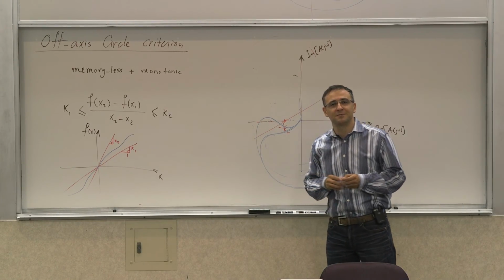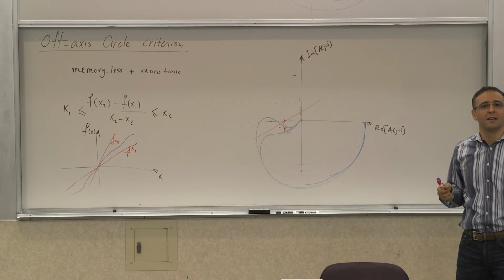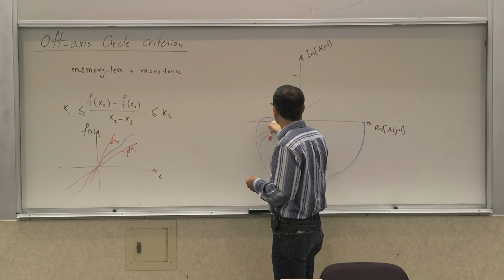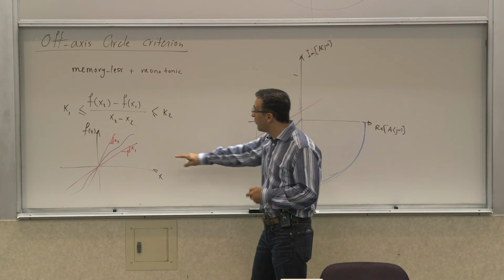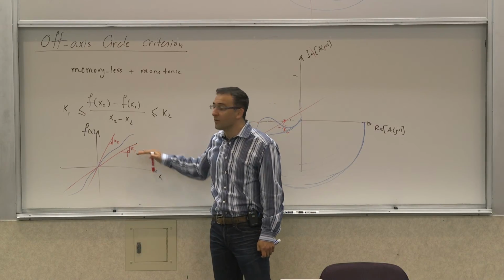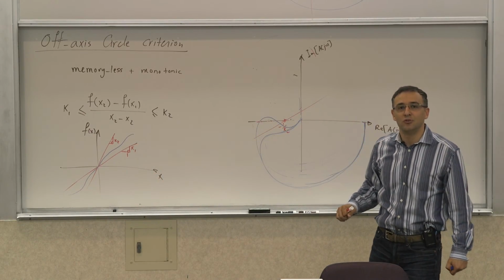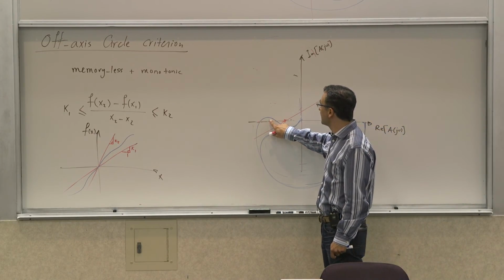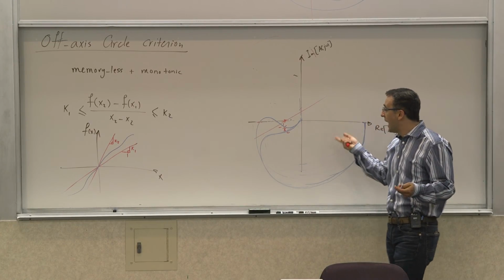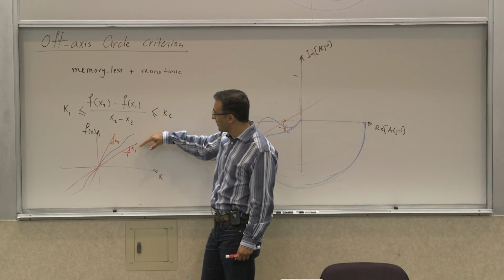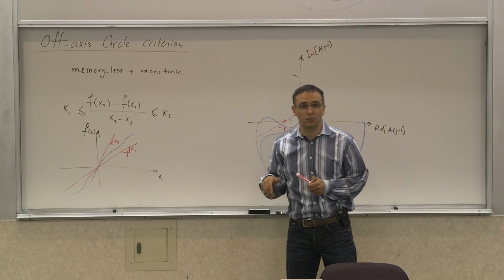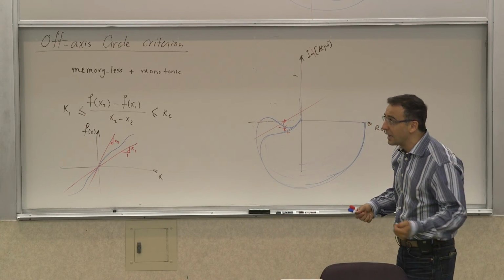Now, you remember this? This could be, for example, a conditionally stable system from a linear perspective. But now, there's no line you can cross here if k1 is 0. So with a nonlinearity that has a minimum slope of 0, all of those conditionally stable systems will not necessarily be stable. So we can't guarantee stability for any of them, at least using this criterion. However, if you can limit your k1 so it doesn't become 0, it can be even a small number, then there are a lot of cases where you can actually create a situation where this will be stable. So this is a more accurate way of thinking about stability.